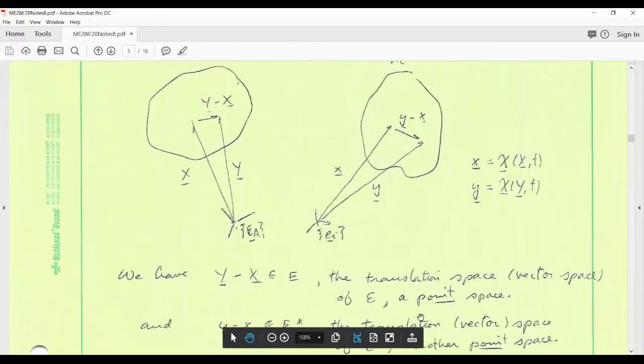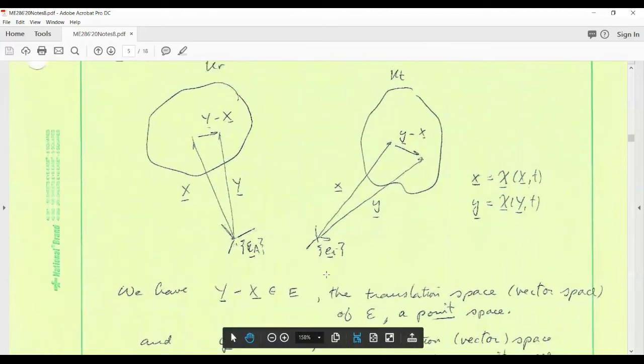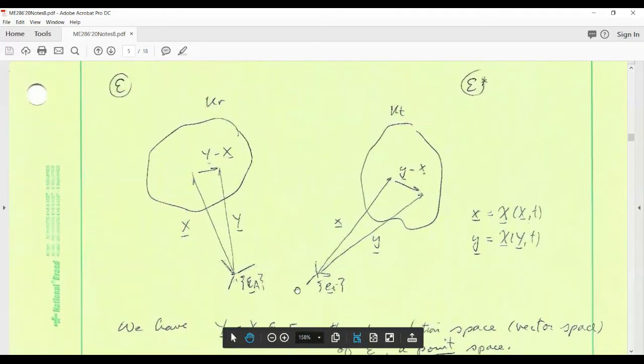So to emphasize the point here, I'm introducing a basis, capital E_A, as we normally do in elementary continuum mechanics, as a representative, say, Cartesian basis associated with the vector space E, and small e_i as an example of a basis associated with the vector space E star. And it's conceptually helpful to distinguish E from E star.